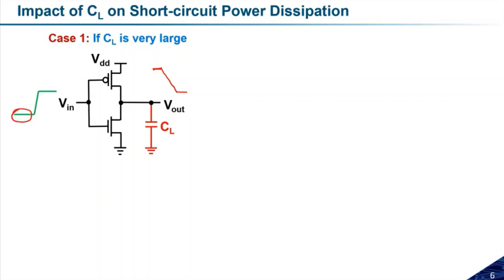Under this constraint, the input moves through the transition region well before the output starts to change. Because the rise time is very small, the input will change from 0 to 1 suddenly, but the output will start changing just after this. The capacitor will not change sufficiently, even though the logic has changed from 0 to 1.